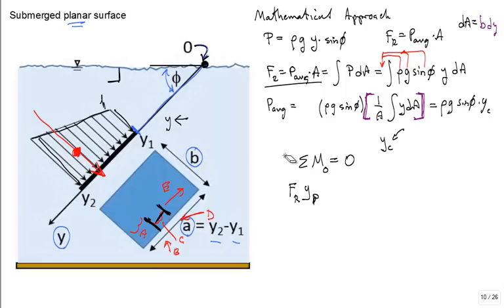I'm going to now use this equation to solve for what y sub p is. The center of pressure, where I need to apply F of R. Well then, it's going to be the same as doing the moment of a little distributed load. What are the units on the moment of a force? Distance times force. True? So don't forget, put the distance and then the little dF, the sum of little chunks of force. But the little chunks of force are due to the pressure and the little area strips, P dA.